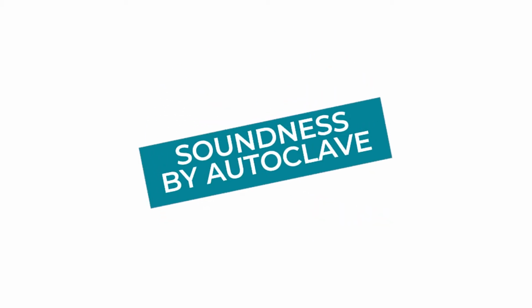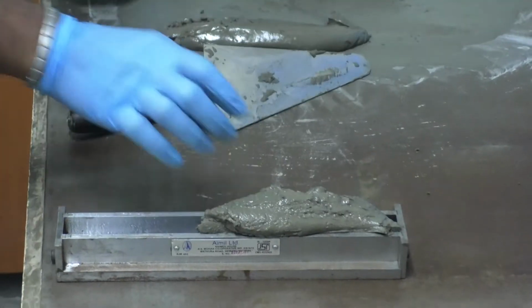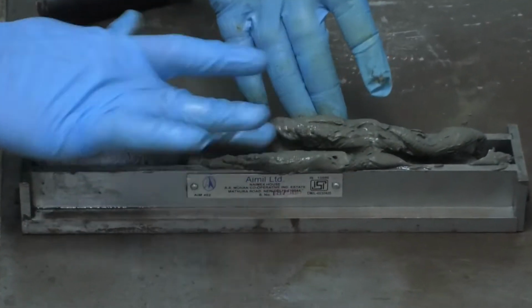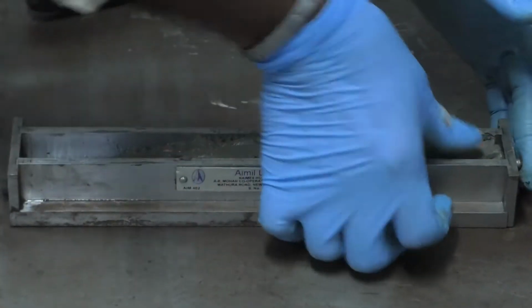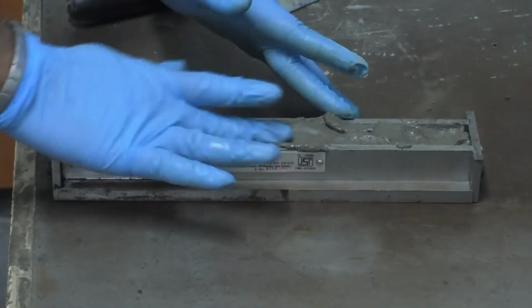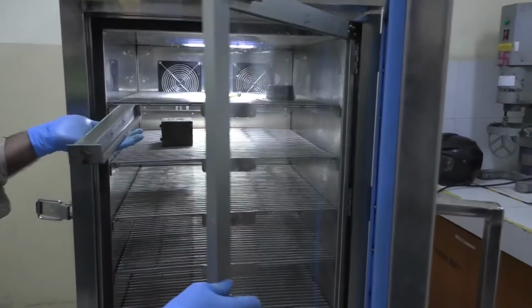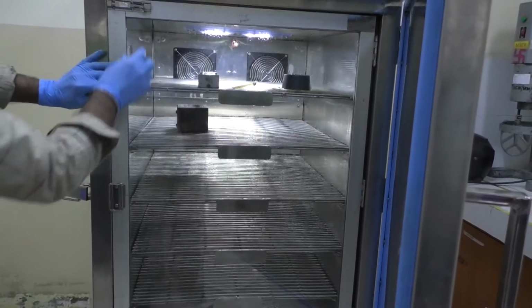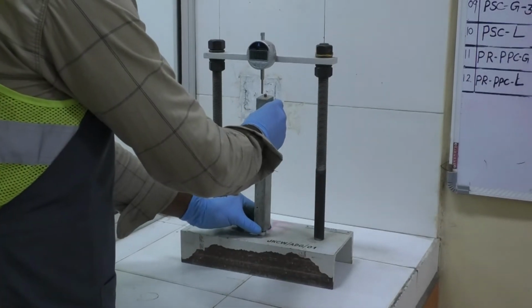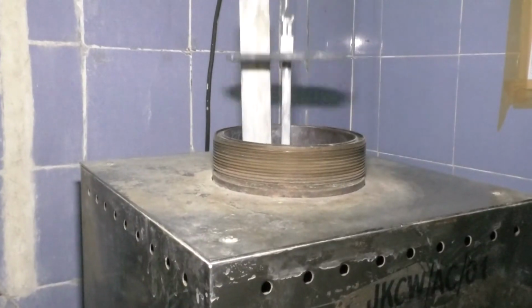Soundness by autoclave. This test is performed as per IS 4031 Part 3. Cement test specimens are prepared in a 25 x 25 x 250 mm mold with water equal to consistency. Specimens are cured in the mold at 27 ± 2 degrees Celsius and 90% RH for 24 hours. Remove the specimen from the mold, measure the length with a length comparator and place it in the autoclave.